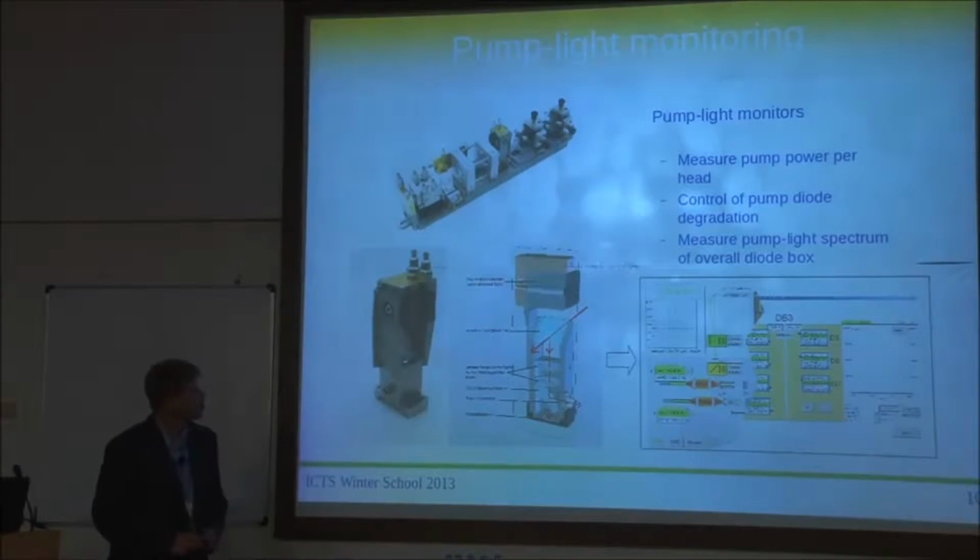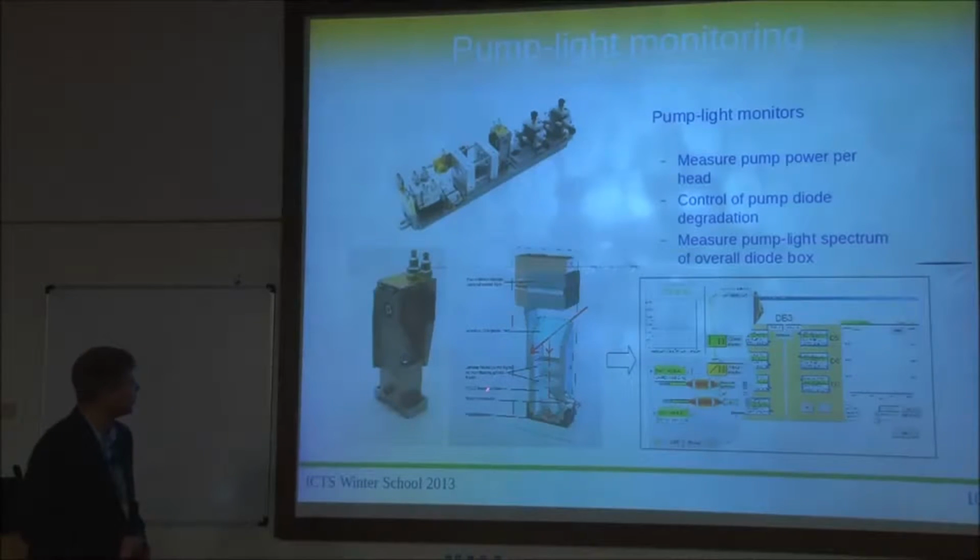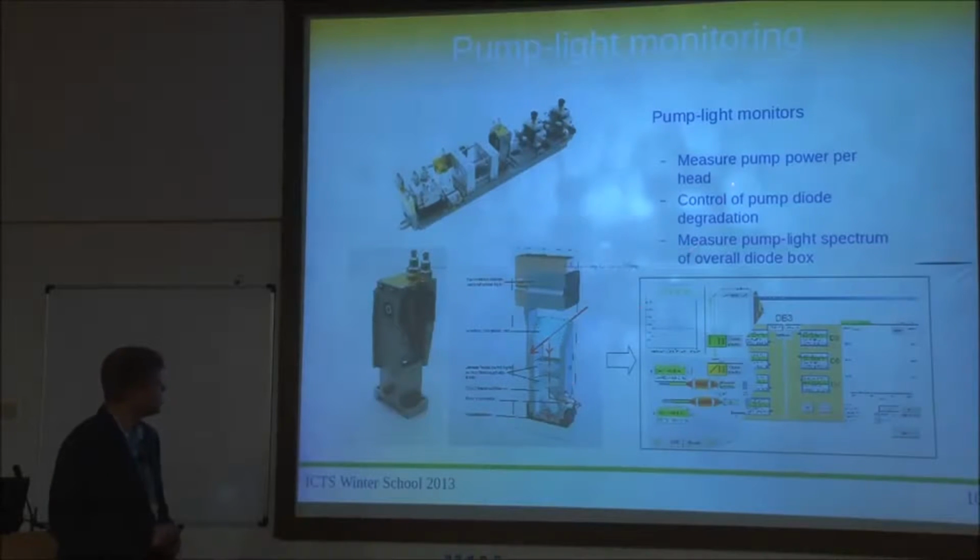We have a little pump light monitor. I commented on that yesterday. So this is one of the pump heads here with the pump light coming from here, and then that's imaged into the crystal through this dichroic mirror. And there's this device here in the middle which actually monitors the pump light. I'm sorry for these crappy descriptions here, but the light is coming from here, and then there's an AR-coated window in it, and a little fraction of that pump light of this 250 watts is reflected here and then sent downwards.